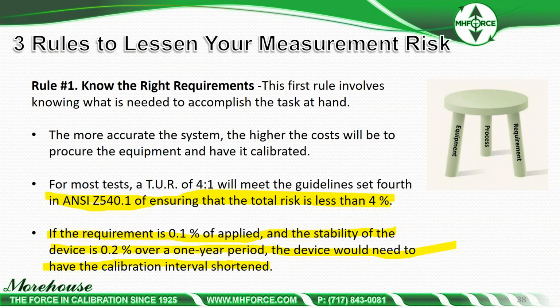At some point, some auditor or someone else should look at this and say, hey, what you're claiming is wrong, because the stability of your device, every single time it goes back, it's adjusted. If they would just up their tolerance to 0.2%, they're probably not going to have adjustments, and most likely they're going to be in tolerance for the stability period between recalibrations. But people forget about that all the time. They just look at what it is at the time of cal, 2 years, a year, 6 months, it comes back. If it's not maintaining that tolerance, guess what? You need to raise that tolerance.